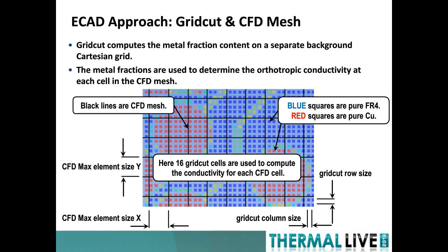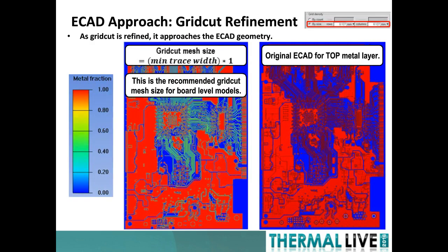As the grid cut is refined, it approaches the ECAD geometry. The recommended grid cut mesh size is on the order of the minimum trace width.